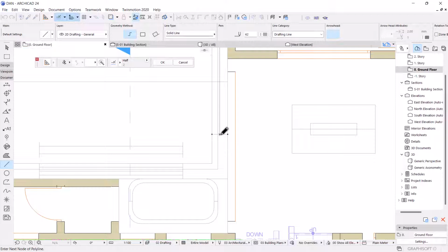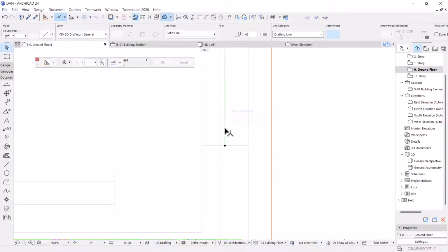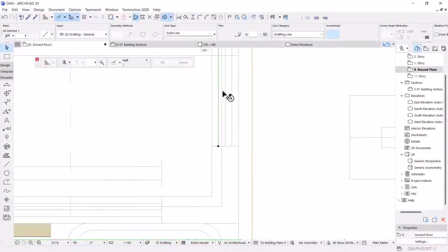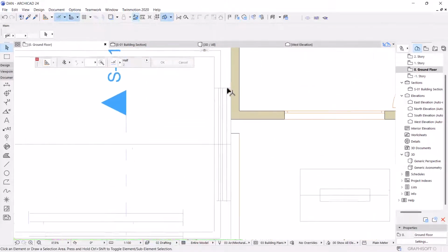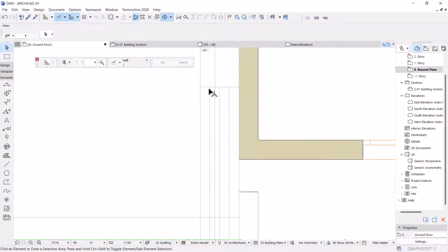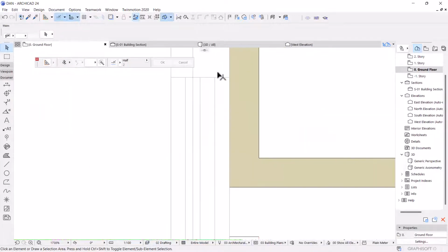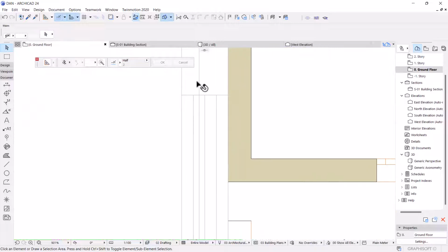I'm gonna press Ctrl+Shift+D, which is 100 mm, and then I mirror this line using the center line to the other end. So to that point, we are okay. Yes, so far so good.